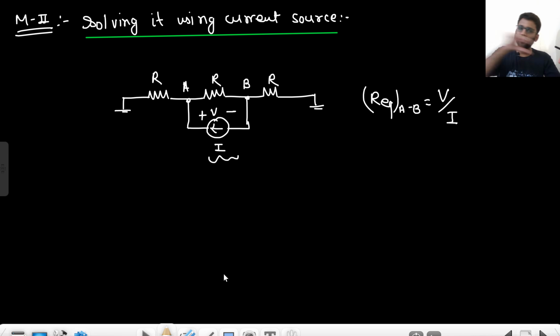Analyze the circuit, get your results. Then add up those results. You will study it completely, with many examples, in the network theorem chapter, which will be the next chapter. But here I am just telling you, consider only one source and get your results, then consider the other source and get your result. We will see it here.